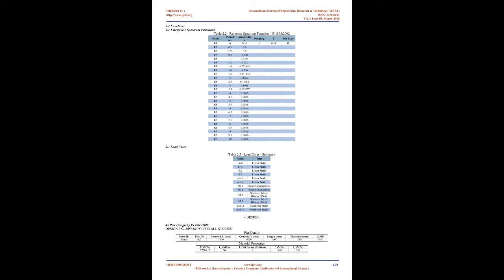It has been concluded that for maximum earthquake structure of 15-story is most stable structure, and for maximum wind effect triangular structure of 15-story is most stable. For 45-story circular and rectangular shape building is most stable for maximum earthquake and wind effect respectively. Wind effect is critical for 45-story building, and on the other hand seismic is critical at 15-story and 30-story building. Wind effect is more critical than earthquake.